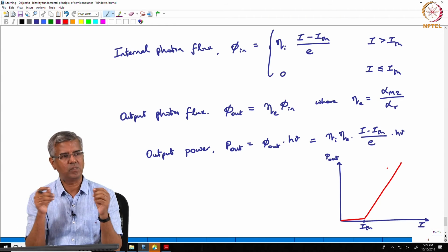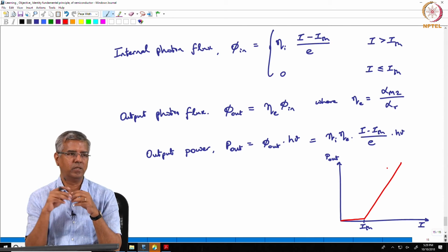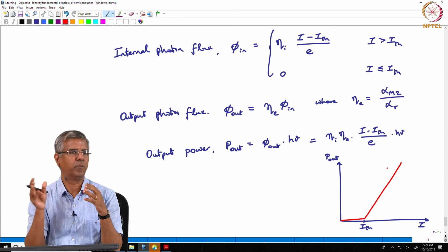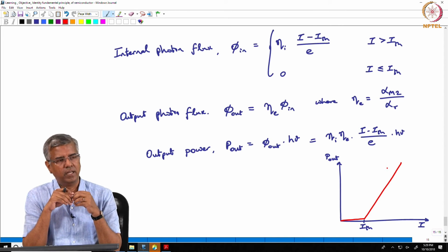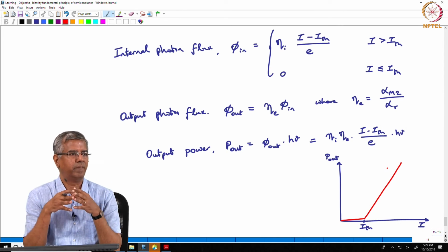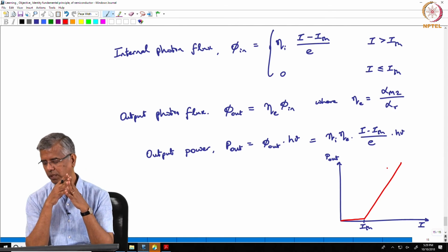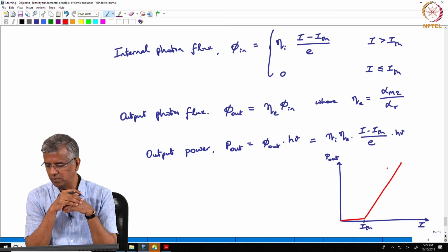With semiconductors, by changing the material concentrations and mixing different materials, you can get band gap energies over a wide range. So you can achieve lasers over a wide range of wavelengths. You choose the corresponding band gap energy and then you achieve lasing at that particular wavelength.